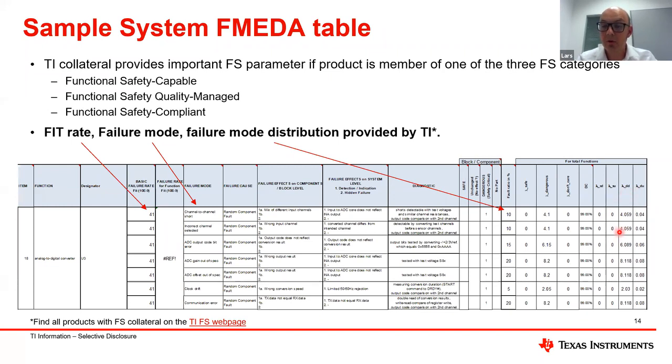And at the end, we apply this to all. They are all 99% in our case. So this means out of the 41, only 1% remains, which means 0.4, 0.4 is the fit rate of our A to D converter. And believe me, if you have a single channel architecture, you have to do much more in terms of diagnostic to reach such levels, right?